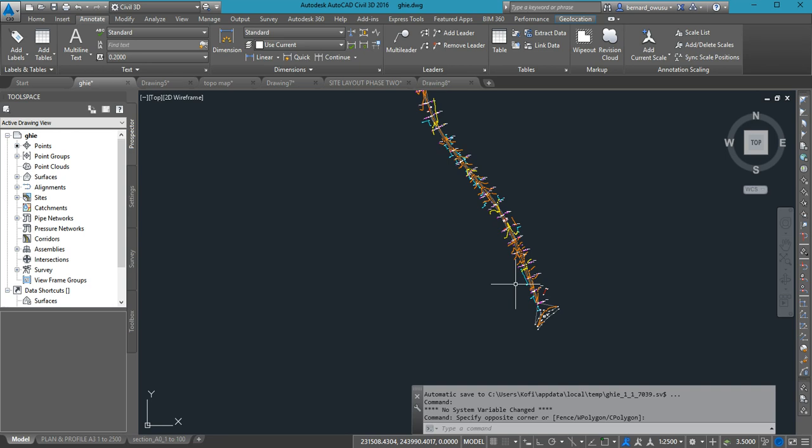Then after the walkway, we may have a drain, it may not run through, but let's say a drain of width 1 meter. So for both sides, we have 1 plus 1, that is 14.3. So at worst, if we are even to go through town, the minimum width that we should have should be about 14.3 meters. That is about 7.15 for each side. So please take note of that value.